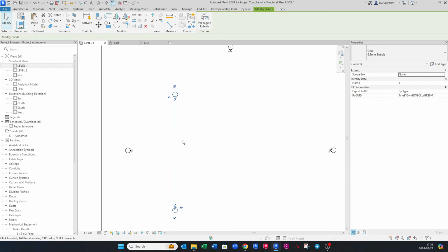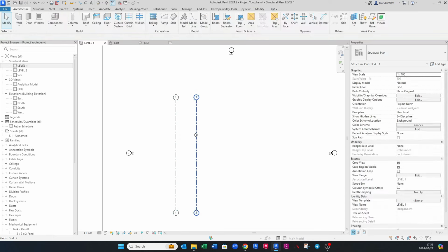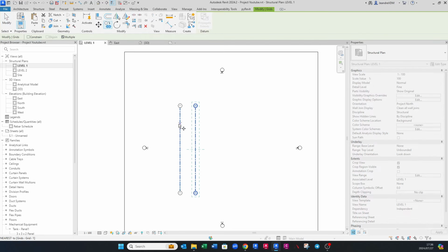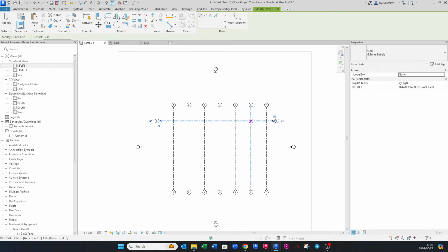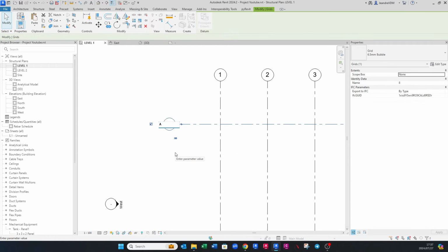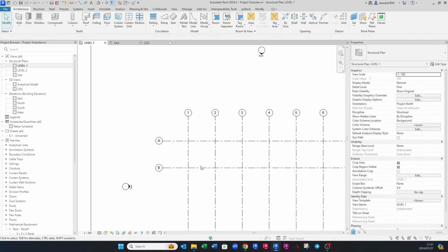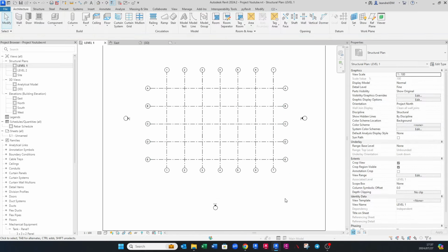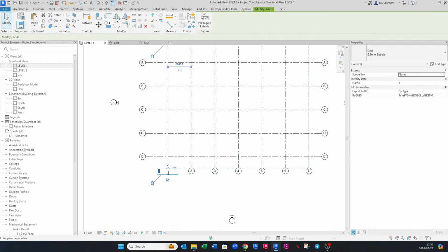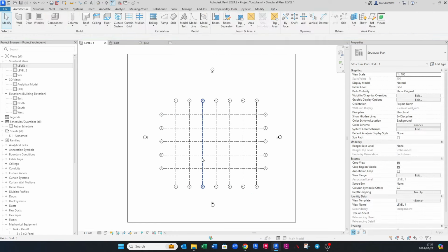So let's just start by doing some grid lines to help us with some references. We'll just put it at 5 meters spacing. Like I say, nothing is in a particular order or anything like that. It's just as I go, I make stuff up. So let's go A. Let's just make this also 5 meters. Maybe a rectangular type of building that we're trying to do here. Okay, I want to snap. That's it. Yeah, that looks okay.